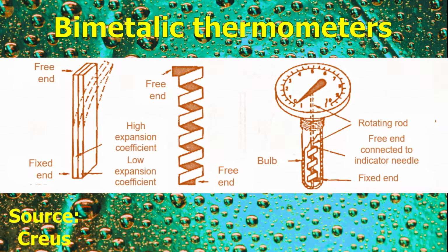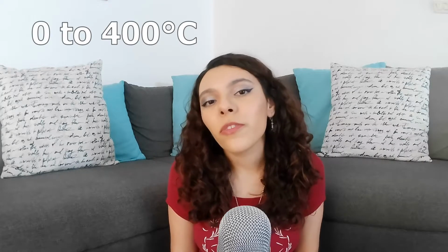A typical bimetallic thermometer contains few moving parts, only the pointer attached to the free end of the coil or helix, and the bimetallic element itself. The shaft and element are supported by bearings, and the assembly is precision built to avoid friction. There are no gears that require maintenance. The use of bimetallic thermometers is permissible for continuous service, from 0 to 400 Celsius.